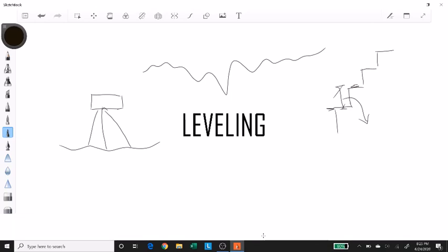What you get from the instrument is that it has a telescope attached, and when you look through the telescope, it magnifies your vision, and the vision you get is something like this: a telescopic vision with crosshairs in the center. What you are trying to view is a bigger version of a foot scale, called a leveling staff.